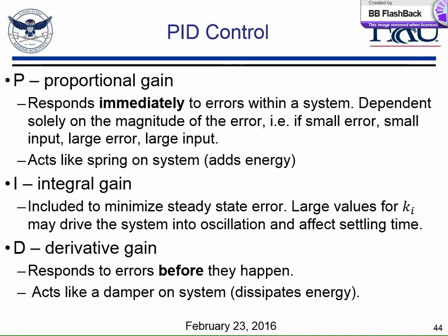As controls engineers, that's what we want to do. We're playing around with poles all day, right? Typically, from our performance requirements, we're able to derive what our poles should look like. From that, we can determine what our characteristic equation should be, and then we can tune those gains appropriately. Or we can use the PID tuner tool and let MATLAB do that for us, right? With the PID tuner, you'll be able to take in pretty much any system and tune it as you'd like.